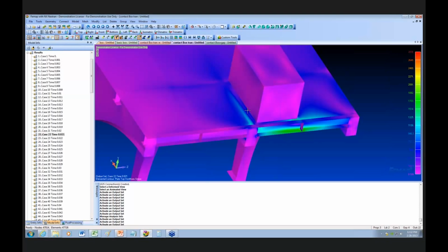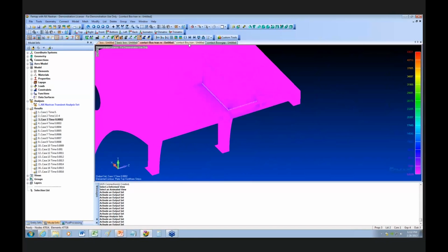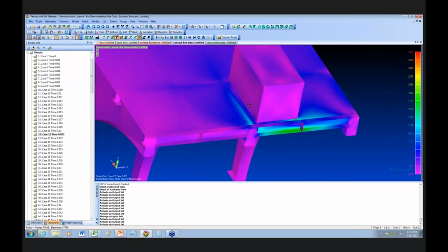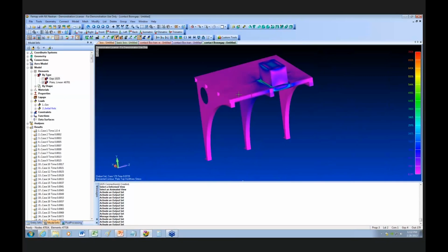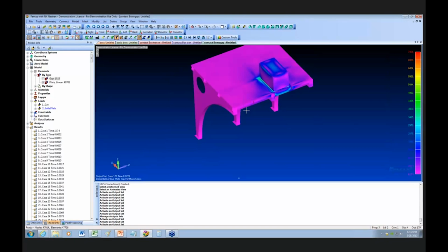You can actually connect the right to the grid points, which I wouldn't do, because again, that's welding it. That's the same thing as R-barring it. So you need some flexibility in between there, and so that's why I use springs for this one. So I used R-bars, which showed bad results, high stresses. I used springs in the transient because that was the closest thing to the gap element. And in the gap element, at contact, it's springs.